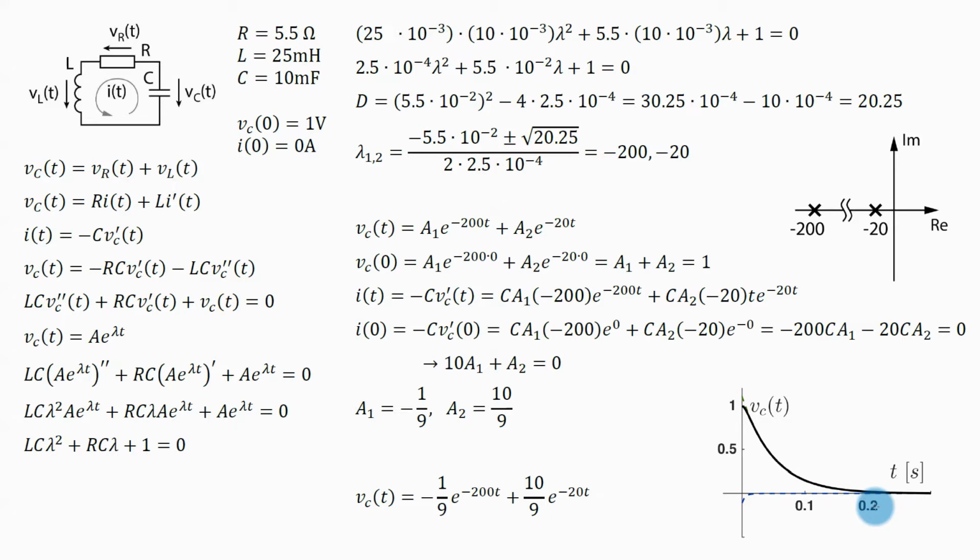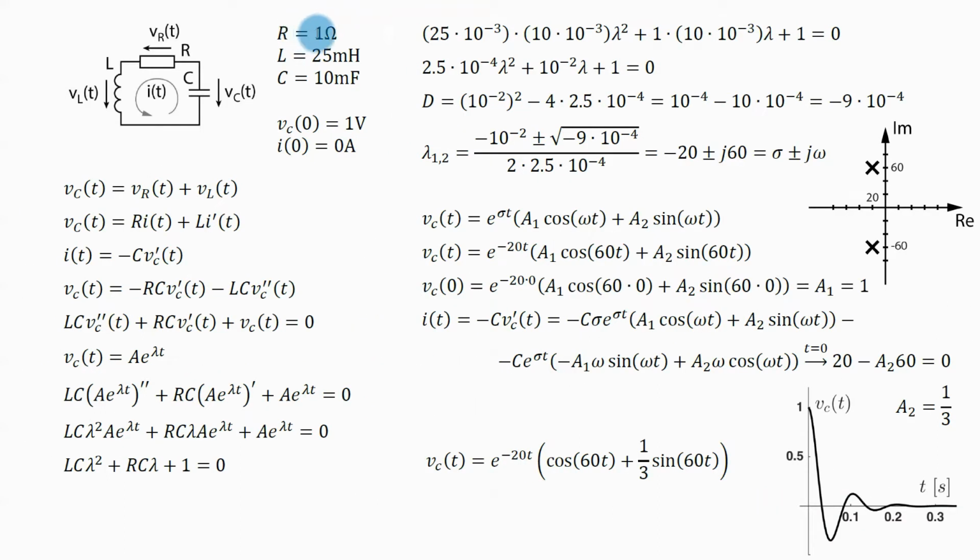200 milliseconds. So this math is confirming kind of intuitive fact that when I decrease this resistance, then this capacitor will discharge faster. But if I overdo it and I make this resistance too small, that is what I had in that first case, when my resistor was 1 ohm, then I'm going to end up with this oscillatory response.